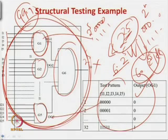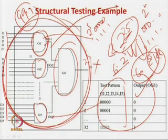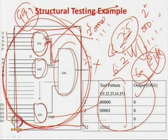This gate, if you want to test, you apply 0, 0, 0, 0, 0, 0, 1 and so forth, this truth table you apply, but you have to observe this output, that this output is connected to this gate, right, and this is the circuit. So this line is directly feeding this AND gate. So this thing is not available at the output to be observed. So one thing you can do is bring this out as a separate pin from the circuit. Then it is very easy, you can apply these 5 inputs and observe this at the output.